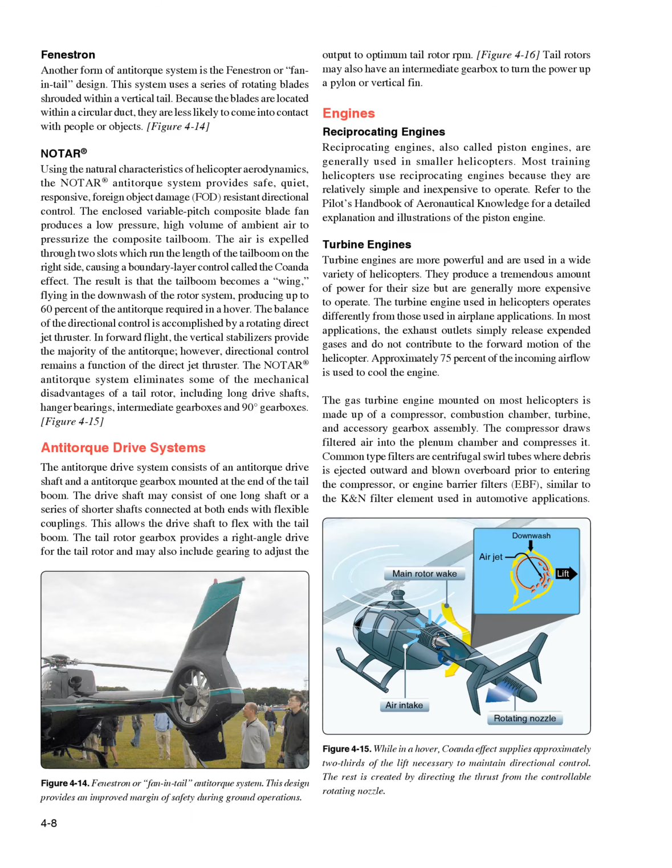Fenestron. Another form of anti-torque system is the fenestron, or fan-in-tail design. This system uses a series of rotating blades shrouded within a vertical tail. Because the blades are located within a circular duct, they are less likely to come into contact with people or objects.